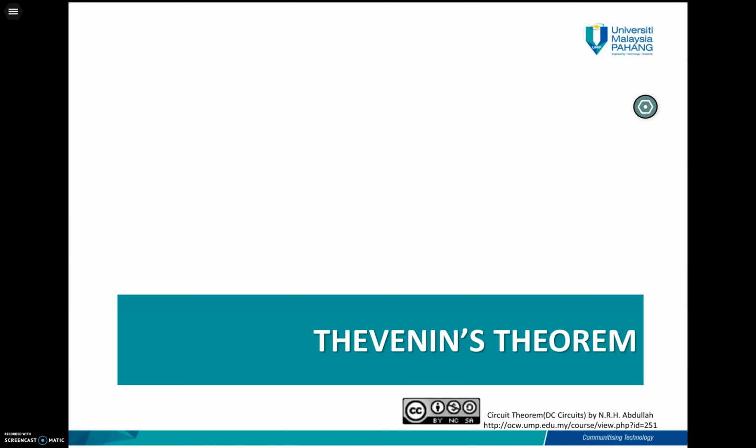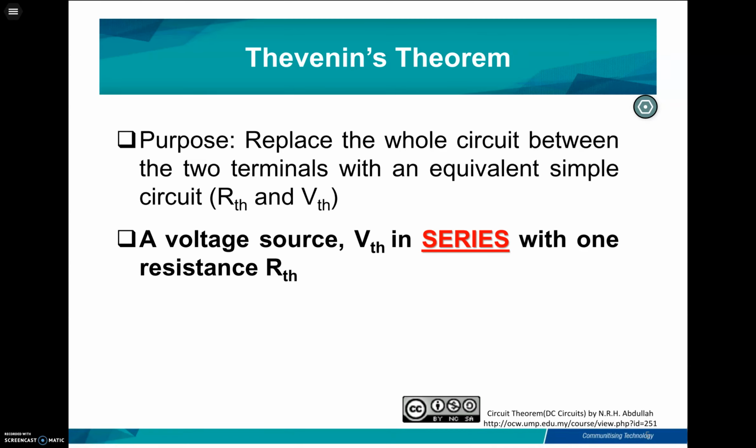Let's start with the Thevenin theorem. What is the purpose of the Thevenin theorem? Thevenin theorem is used to replace the whole circuit between the two terminals with an equivalent simple circuit, R Thevenin and V Thevenin: a voltage source VTH in series with one resistor RTH. TH stands for Thevenin.